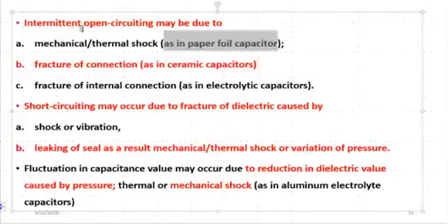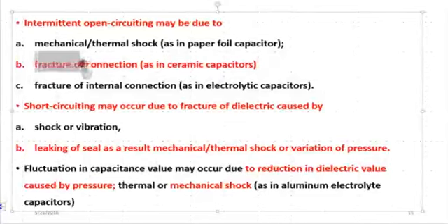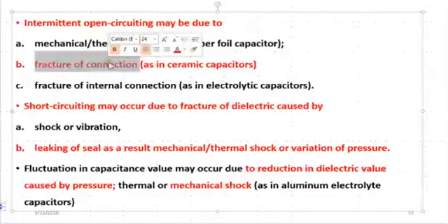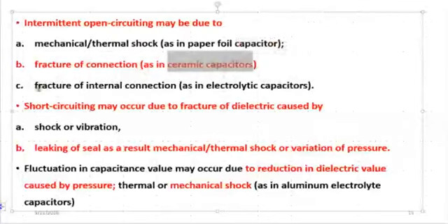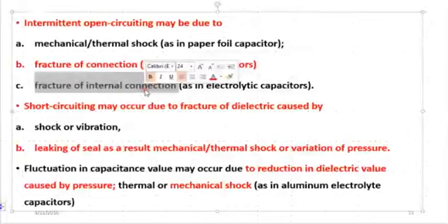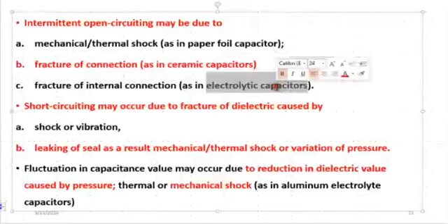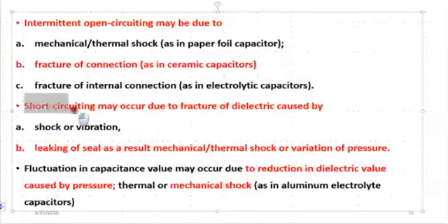Then another cause of this open circuiting is the fracture of the connection, that is breakage of the connection, and it is common in ceramic capacitors. We also have the fracture of the internal connection, which causes open circuiting, and it is commonly happening in what? Electrolytic capacitors.